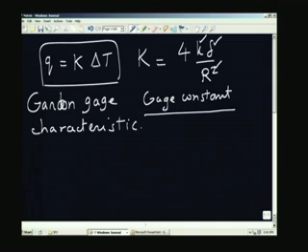So, by a suitable choice of delta and R squared, and the material of course is constantan foil. Once you choose the constantan foil, the thermal conductivity is already known, there is no change in that, it is going to be about 20 watts per meter degree Celsius. So, the thermal conductivity is fixed. What I can do in practice is to choose the delta and R combination such that I get the desired value of capital K and the desired value of the measurable delta T. You see that if K is very large, delta T will become small and so on. So, it is a question of having some kind of a balance between these two.